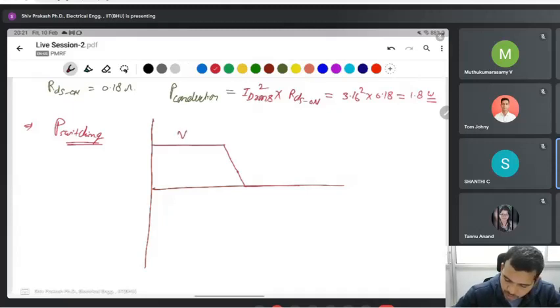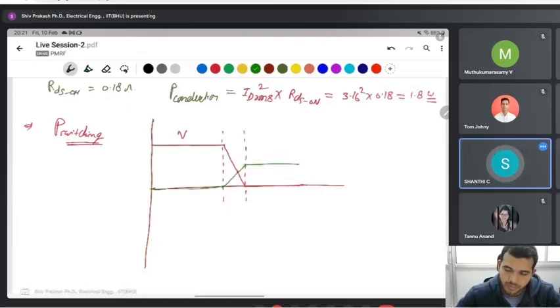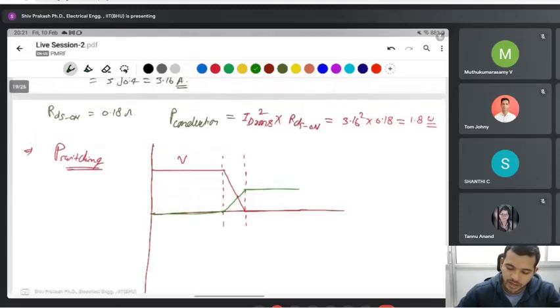Take a look at the voltage. This one, on time. So for the peak conduction loss expression, you didn't include the root of duty ratio? Yeah, including duty ratio, because of the RMS. No, you can already find the RMS value of current, then you can directly apply. If you have a peak value, average value, then find the other value.